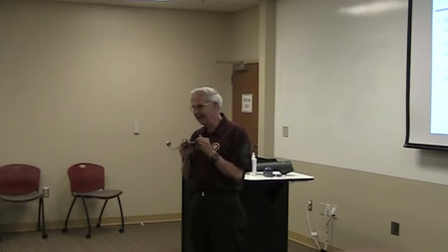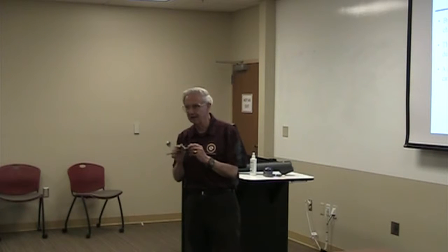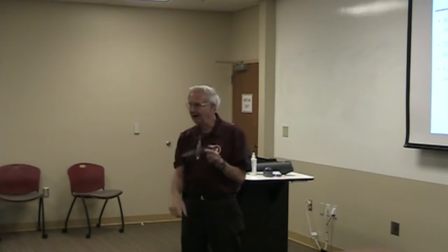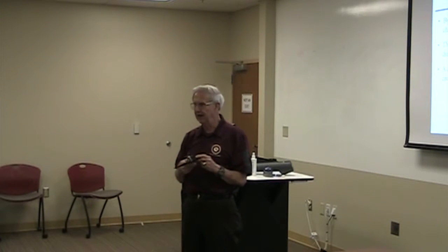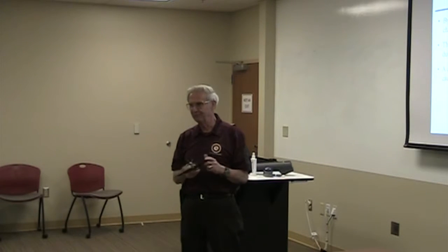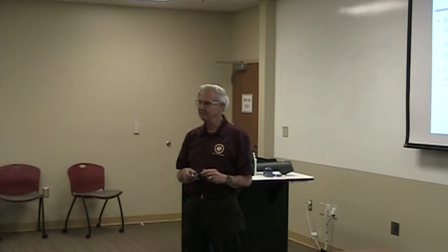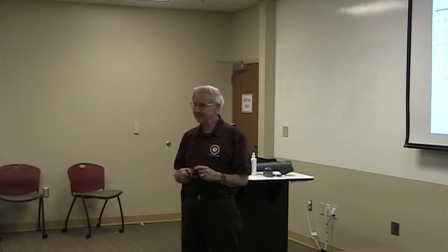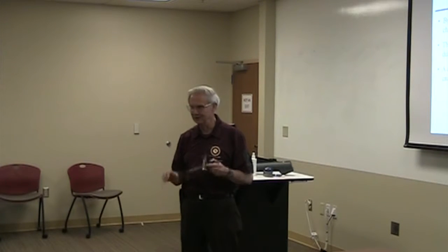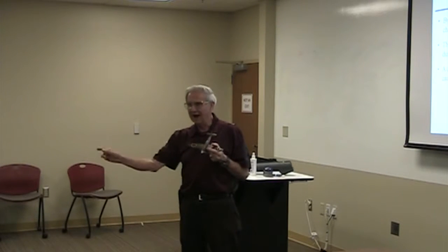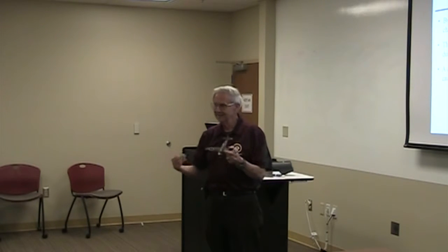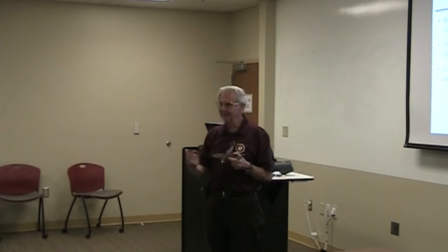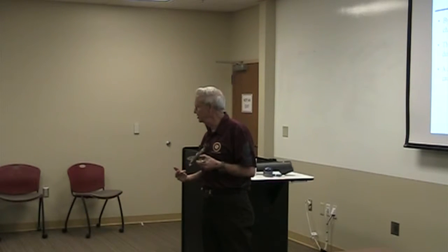So you don't want to get into a rudder lock situation in that case, and of course you're going to need to hold a lot of rudder. As they say in the multi-engine training, dead foot, dead engine. Whichever foot you're not working real hard is the dead engine side, okay? If you've got your right foot in there, it's the right engine that's running, and the left one is dead. That's the initial way you quickly identify which engine failed. You have an engine failure.